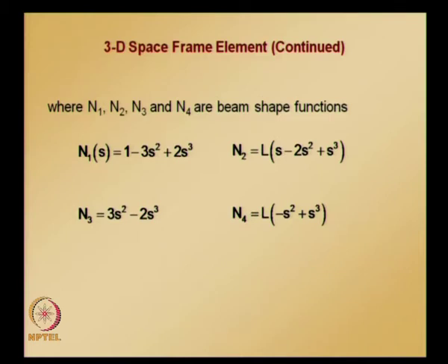And using an approach similar to what we did when deriving equations for the beam bending problem, it can be easily shown that the bending moment is given by this and the shear force is given by this. The only difference is that a negative sign is getting appended, and substituting shape functions into the beam bending potential energy functional, the following equations can be easily derived by applying the stationarity condition.